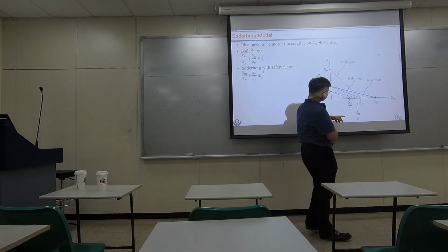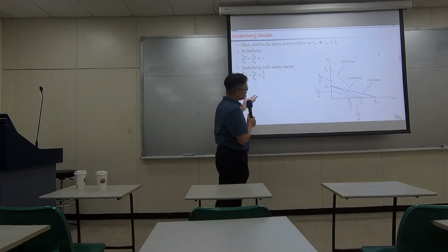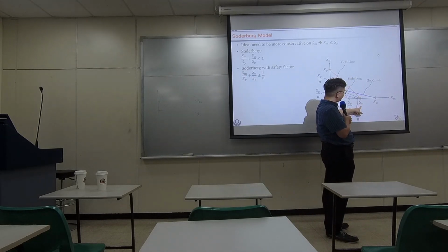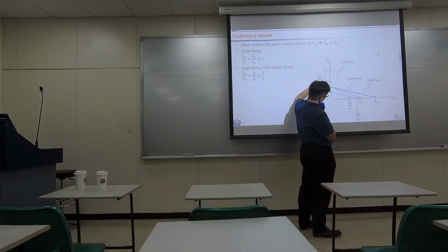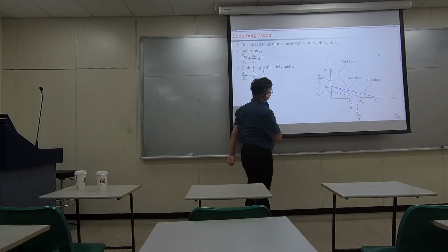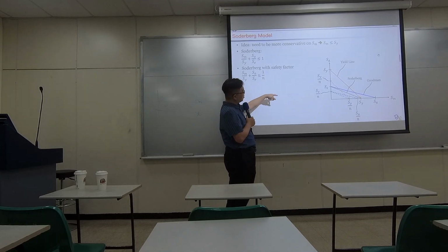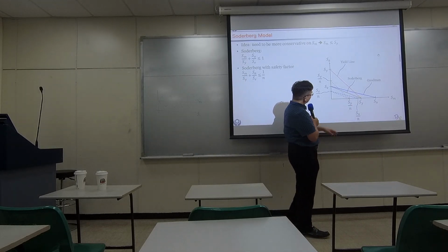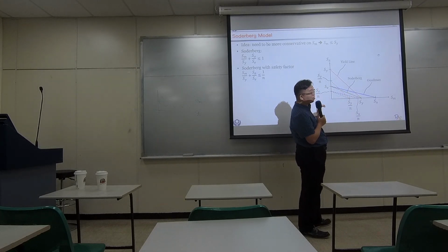design for fatigue. So basically, we're looking for this green line. How do you get the green line? Basically, the mean value divided by the upper limit, which is the yielding point, plus the amplitude divided by the endurance limit must be smaller than 1. And similarly, if you apply safety factor on the right-hand side of the equation, you get the dashed line. Okay, as you can see, when you are more conservative, your design space becomes smaller.